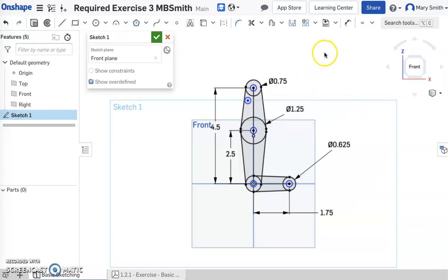It does have a dimension they snuck in here on me that says this circle, that circle right there is 0.25 inches in radius. And now they all have the same 0.25 radius because I made them all equal before this. Everything's fully defined, but this one right here, I need to define its distance. I need to define its position.